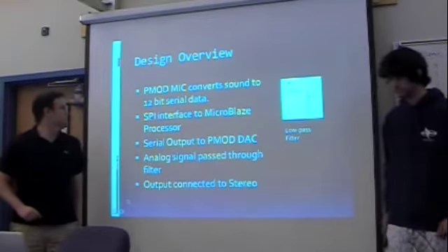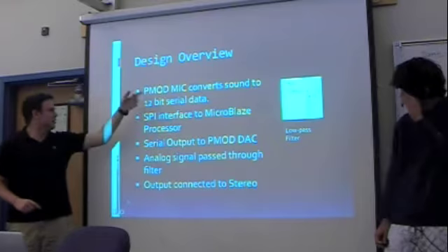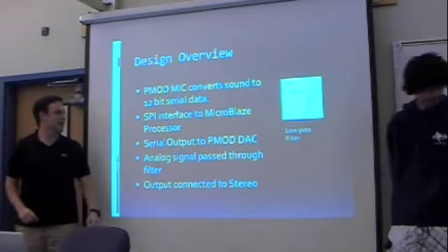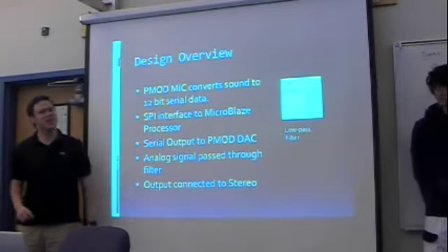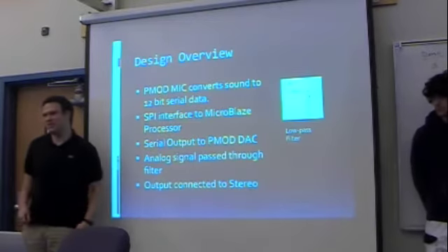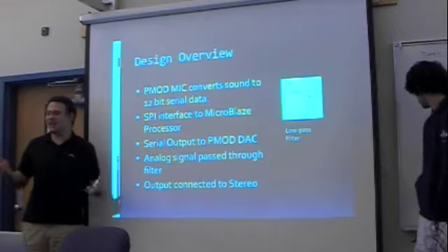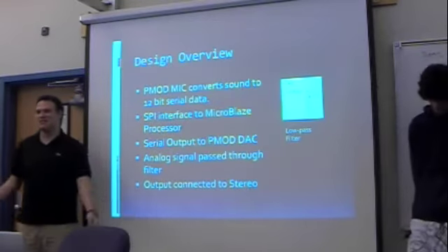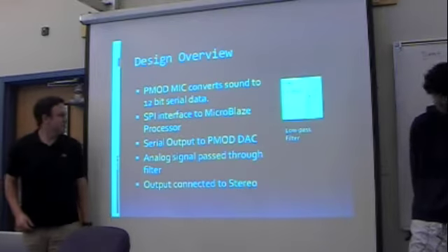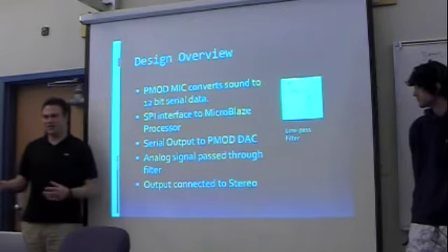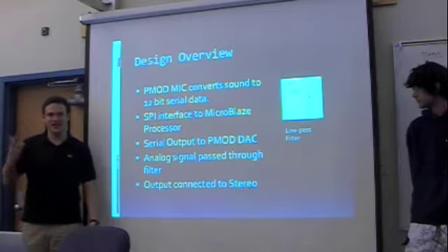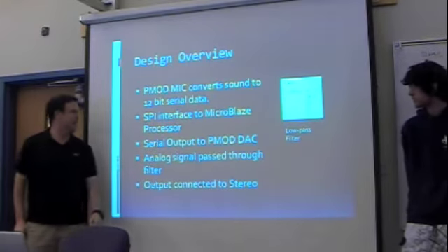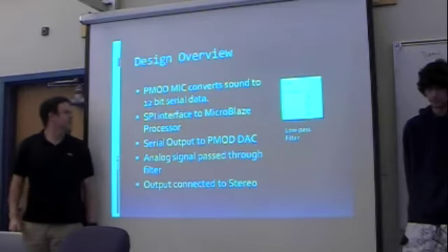Pretty much we do this PMod microphone, so this thing is 12 bits, so we have to use an SPI. But what's interesting with it, when we originally started getting data from it, this is not a great microphone. We got it for like $25. You don't expect that great of quality. When we first ran it, we were getting weird data. There's a lot of noise.